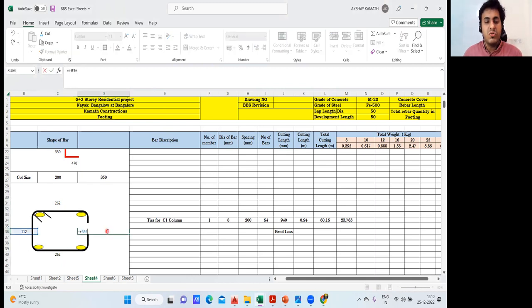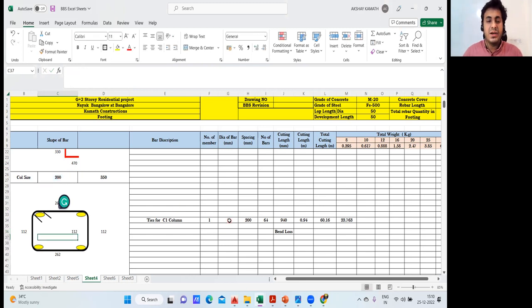This side also you know how you did this. I'll do it here. For this side, what I did, yeah, this side what I did plus what is the length that was there, what is the breadth of that? So breadth was 200 minus 40 mm from the left side, 40 mm from the right side, top 40, minus 40, and then minus one diameter, I told, diameter of the stirrup. I'll get 112. Manually also I got the same thing. Agree with me?